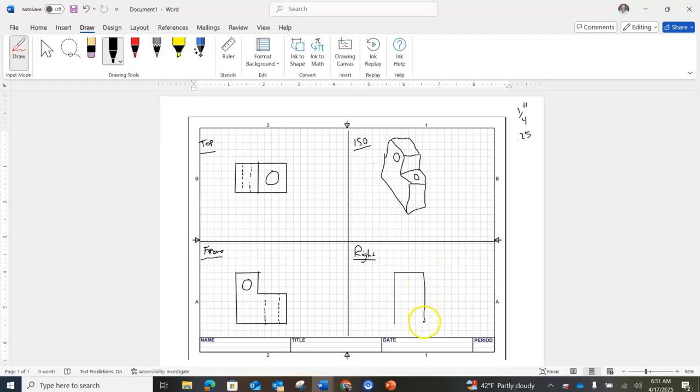Okay? So then I draw this shape out like this. Finish it this way, and you cannot see any holes at the right view, but you can see this object line where it's cut. So we have to represent hidden lines here and here, and then a vertical one. Oops, it would actually be exactly 2 squares wide for our hole that's here. Does that make sense? And so this is what a multi-view orthographic drawing would look like.